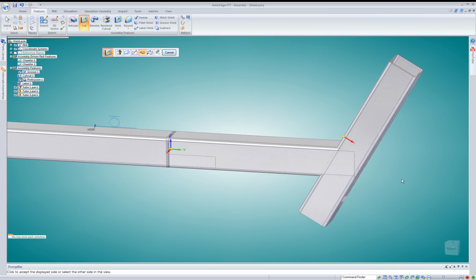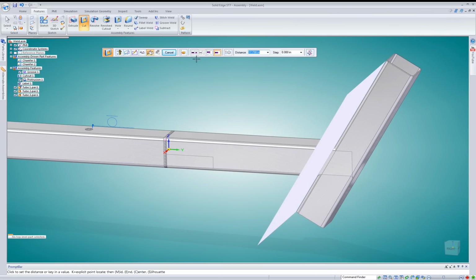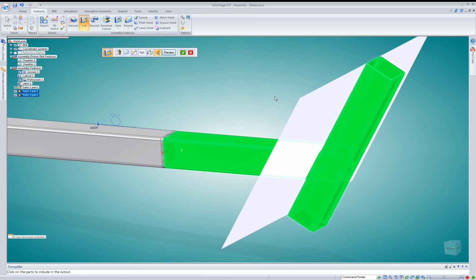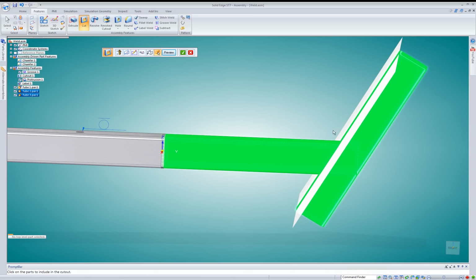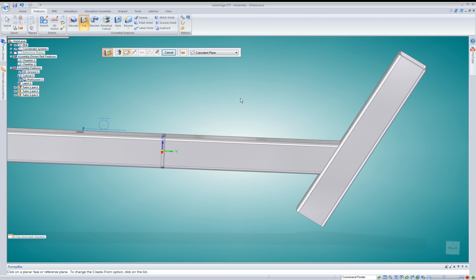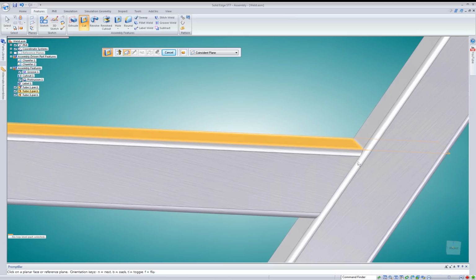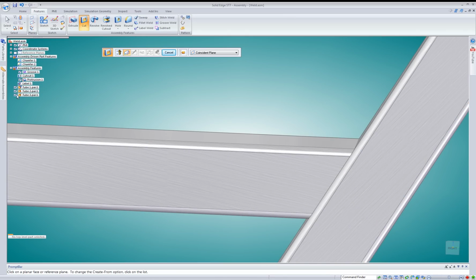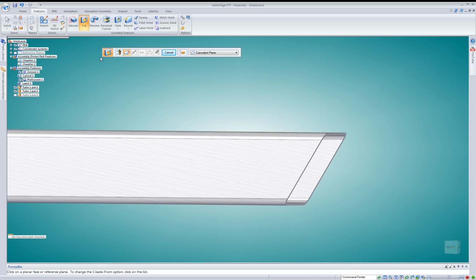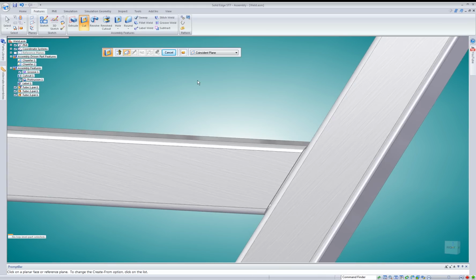Notice we got a little chain link there that says, hey, these two parts have the geometry that's going to tie together. And let's cut this in both directions. So I want to cut, there we go. And again, I don't want to cut both parts. There's no reason to have that selected, so I'm going to deselect that and reselect this guy so it adopts the 45 or whatever 20-degree angle I have there. So now you see, if I turn off tube 3, we get a nice little section cut there.